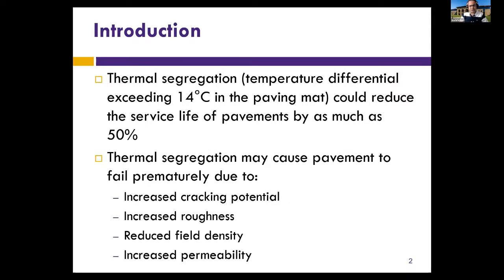If we look at the literature, it has been reported that the areas that have cooler or lower temperature during construction usually will show increased cracking. Also, because of the cracking, they would have increased roughness, reduced field density during construction, and increased permeability. So these particular locations are very prone to premature failure, which can be a major issue because the pavement will require premature maintenance and rehabilitation.